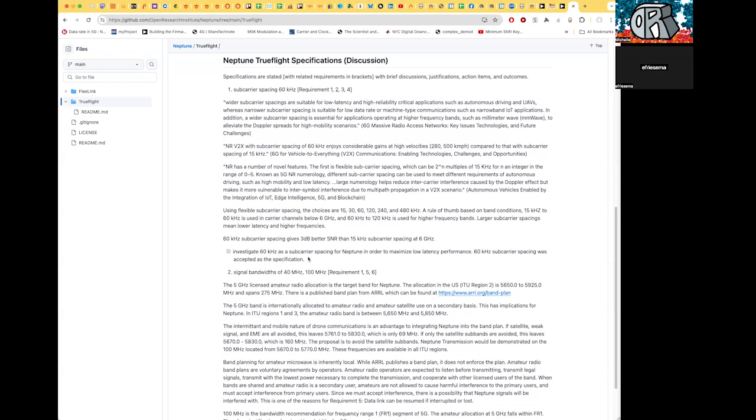I'd really like to see 100 megahertz to deliver the sorts of throughput that we would like to see for first person video. We're limited though, with 40 megahertz being our biggest. That's still really good. So the proposal was, let's say that we have a baseline design of 40 megahertz so that we can demo it in the lab and that we make sure that our protocol will also deliver 100.